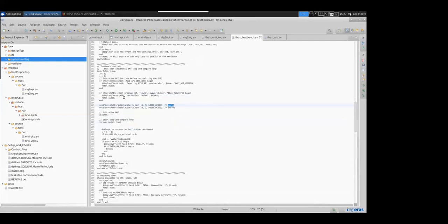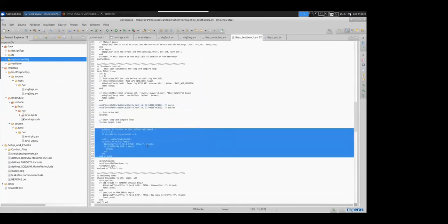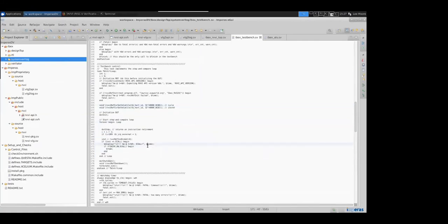And then after the setup, we go through the phase where we're executing the program that's running on both of these representations. In the background, if you remember, because we're driving this RVVI interface, all these API calls are being made across to the Imperas DV environment, performing sets and comparisons in the reference environment.